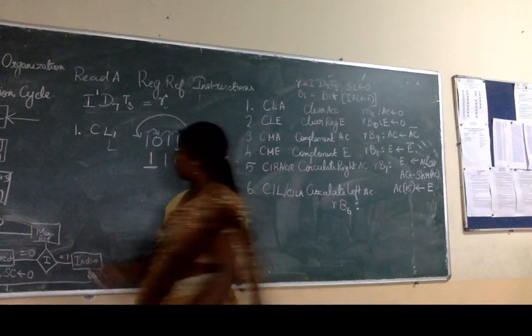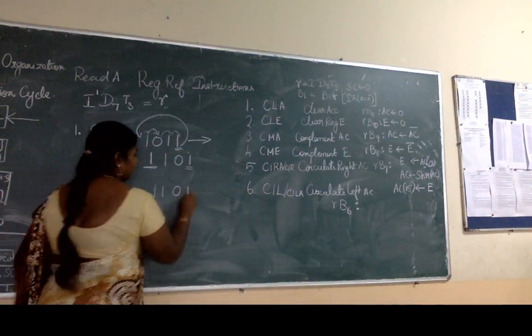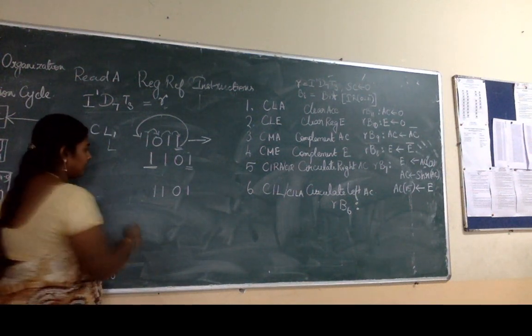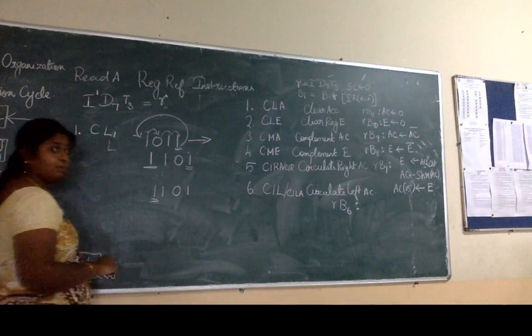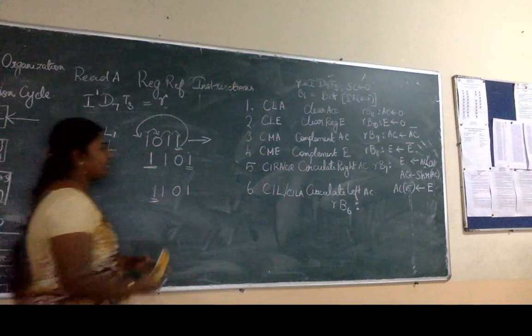In this case, if I try to shift everything towards the left, which bit should I save? Imagine this is my 4 bits that I want to preserve. When I shift everything to the left, the MSB is the one that will be overwritten. So I have to save only the MSB.